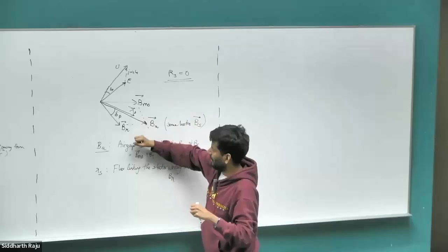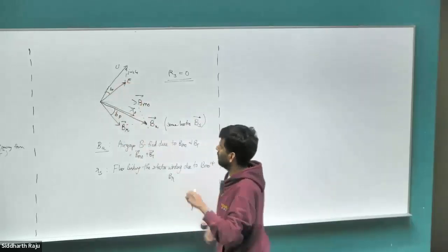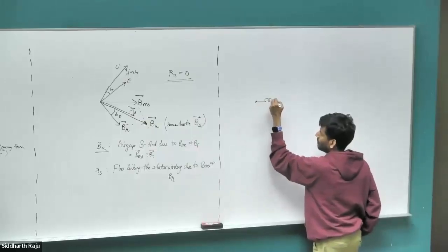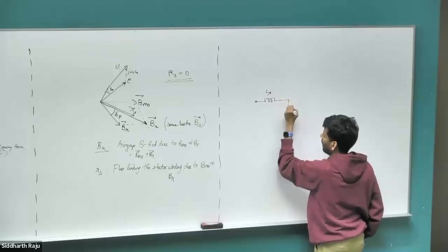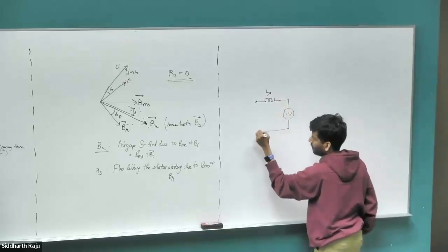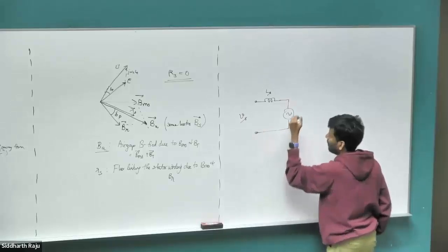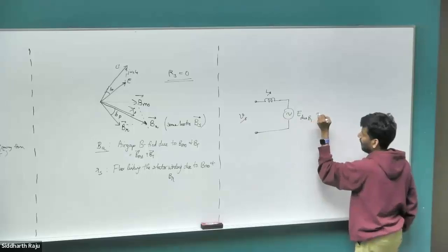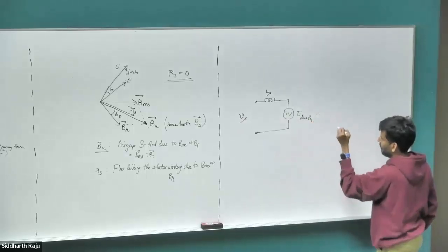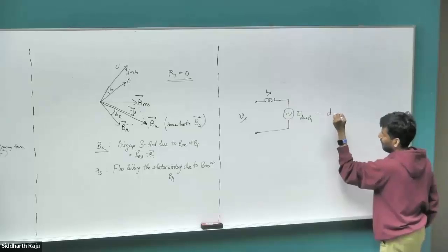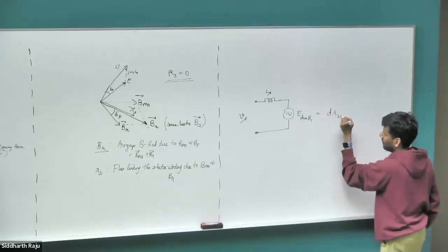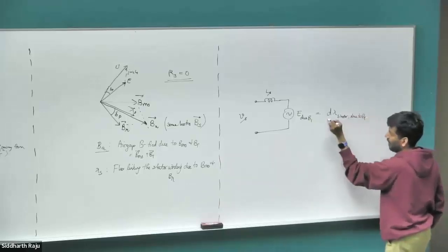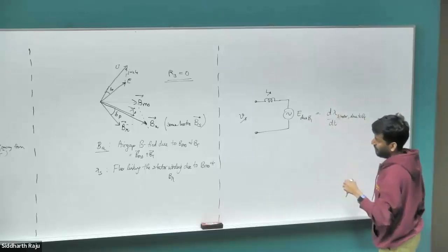So this is going to be an angle, and let's see why this delta P is the same as this delta P for the case where RS is equal to 0. So let's go back to our equivalent circuit: LS, some back EMF, and some VS. How did we get this back EMF? This was back EMF due to BR. And how did we get this? We basically looked at the flux linking each of our stator coils due to BR, and then differentiated that flux linkage to get the back EMF E.